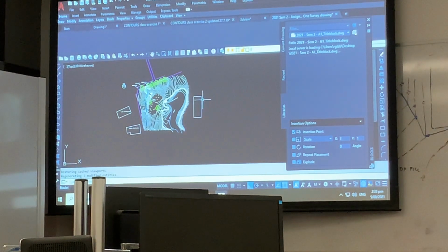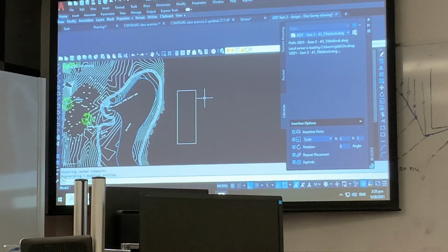There it is there, a perfect place to do my notes, survey data, locality plan, and I know it's going to appear. And the good thing is it's the same scale, 1 to 100, so that means any text type can still be the same. Using 3.5 or 5 for there will still come through at the same scale on the A1.